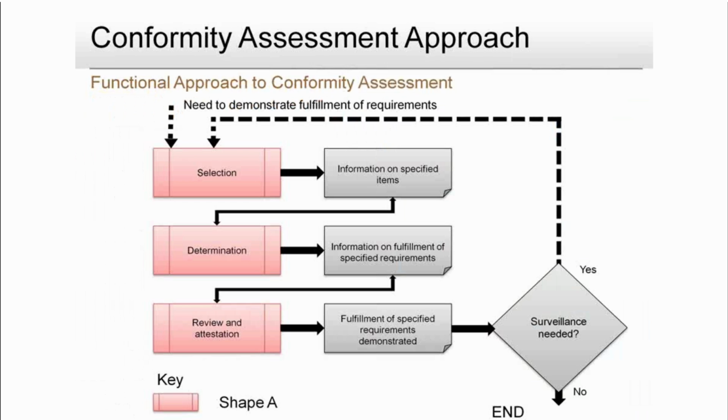Statistical analysis, for instance. Let's say we have repeatability, and we want to estimate it. A good way to do that is standard deviation of a set of repeated measurements. So there are ways to estimate uncertainty. Other means include finding the uncertainty in calibration results, for instance, on the calibration certificate, or ascertaining the value of a reference material from the material certification. So all of this must be strictly followed in implementing ISO 17025.